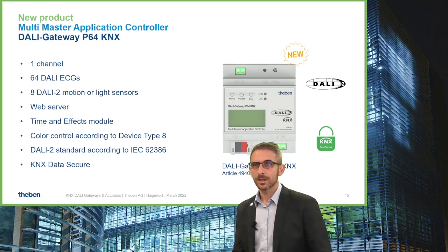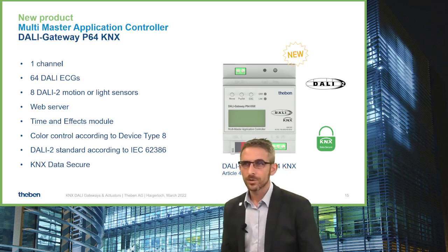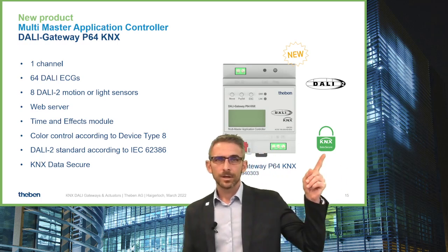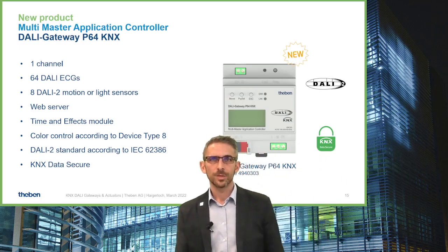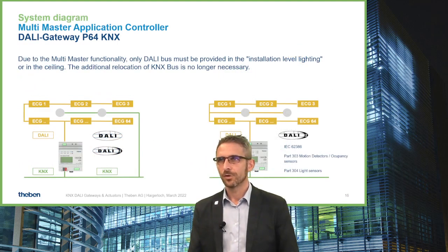Color control is done according to DALI Device Type 8, which is DALI part 209. And yes, we're following the DALI 2 standard. And also this device supports a secure communication in your smart building following KNX Data Secure.